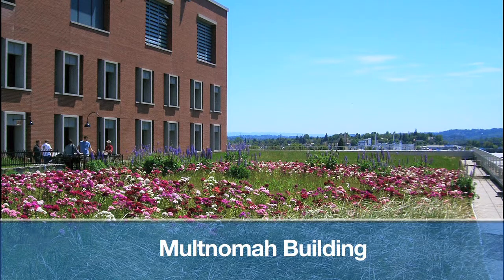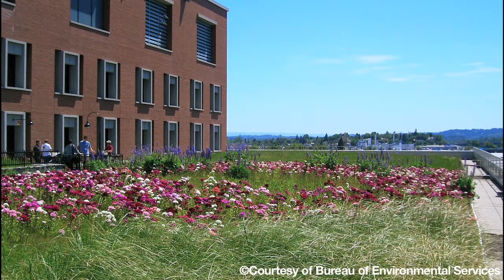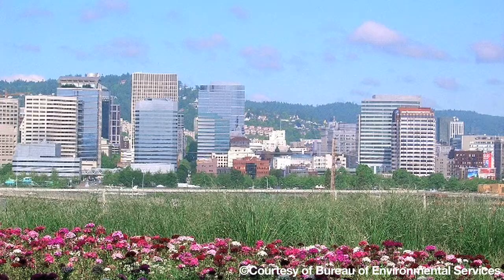The Multnomah Building, also in Portland, Oregon, has a 12,000 square foot green roof that is accessible to the public. The green roof was chosen because of its environmental benefits, longevity, and cost effectiveness over the long term. The roof absorbs rainfall that falls directly on it. The overall stormwater management goal was to reduce the peak runoff and volume that would otherwise contribute to combined sewer overflow events in the adjacent Willamette River.